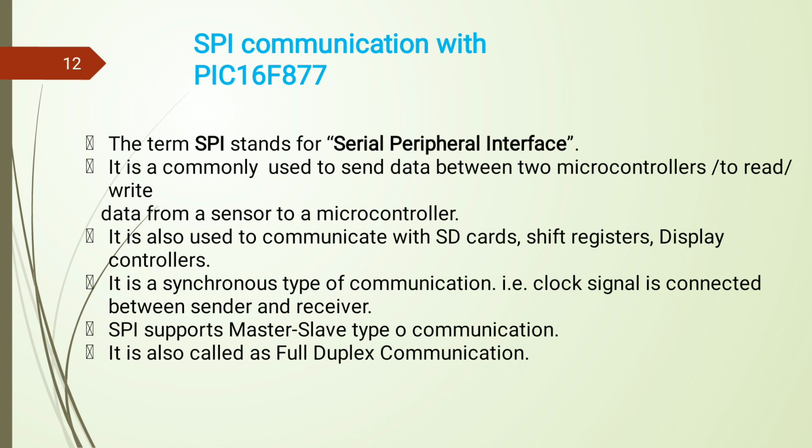In the case of SPI and I2C, the words used for transmitter and receiver are mostly master and slave. The master is the one able to establish communication with the slave, that is the opponent device. The master is responsible for generating the clock between master and slave device, and also initiates the communication and completes the communication with the help of the slave.